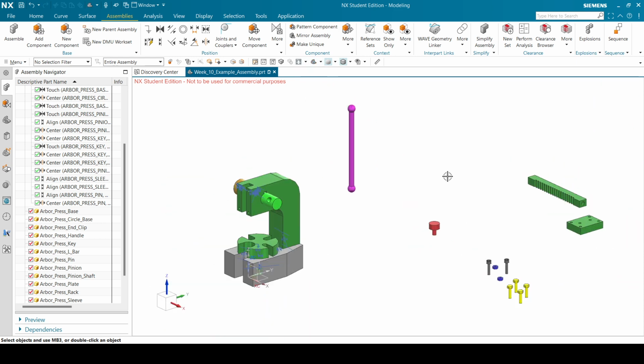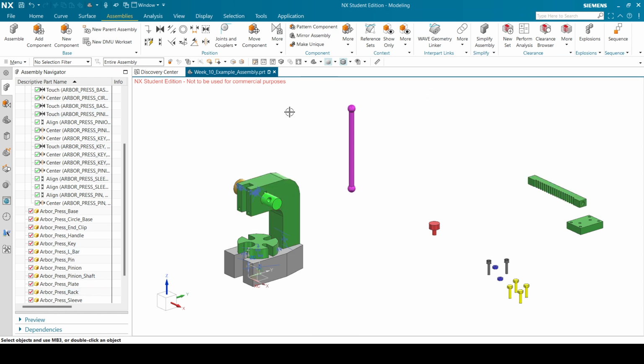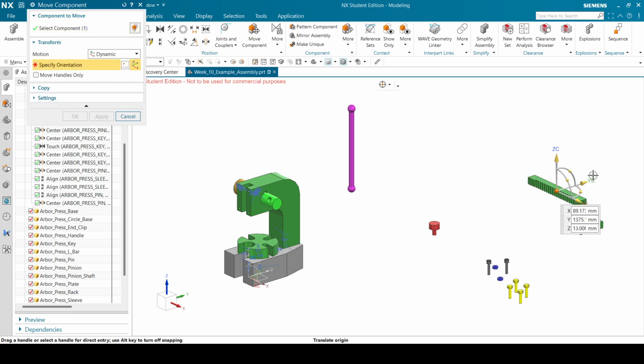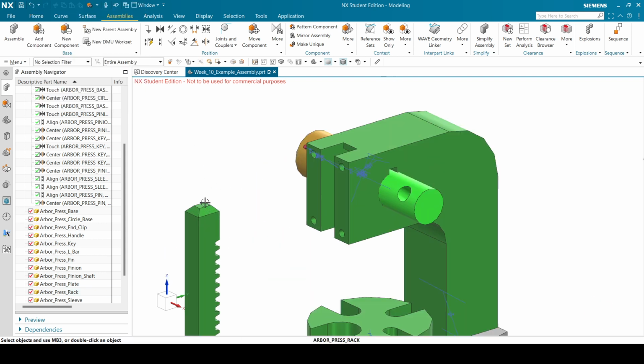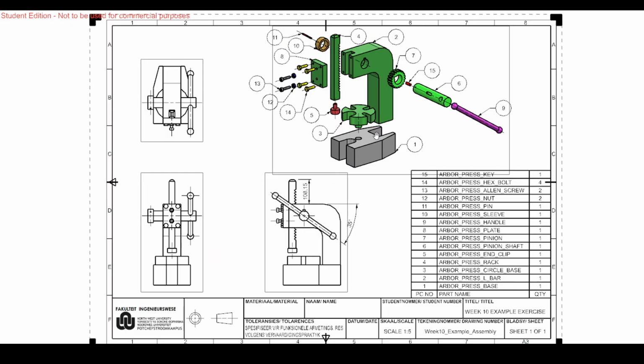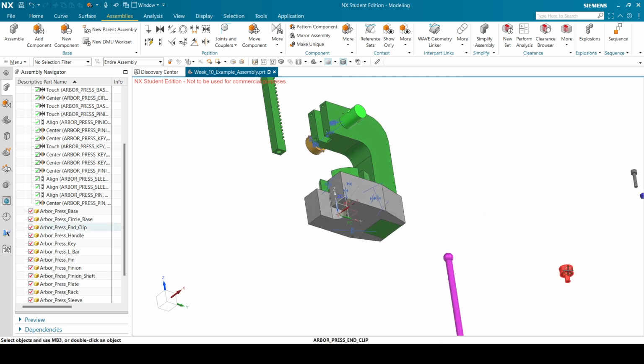So now it's just the last finishing touches, such as functional components. So that it's added in there, and it should be in that slot. There we go. So let's first move it a bit closer. As fun as it is to see NX moving the parts around, sometimes it's just a bit more practical to put it in roughly the correct position first. Okay, so 180 degrees and 90 degrees. So, oops. So take note of this trapezium-ish top, and that's what should be on top over here, because the hole at the bottom, that one, is for this to interface with.